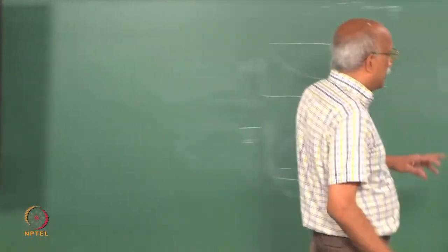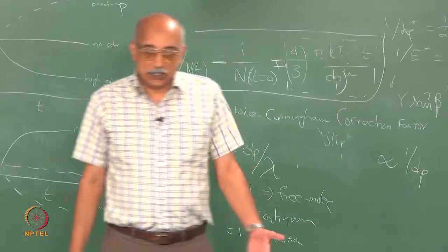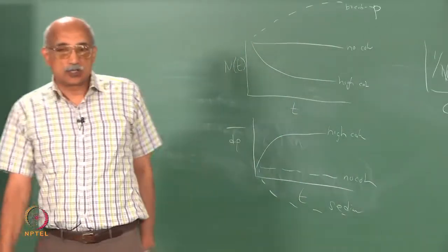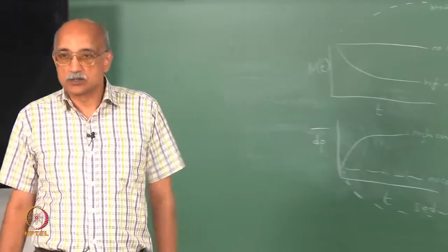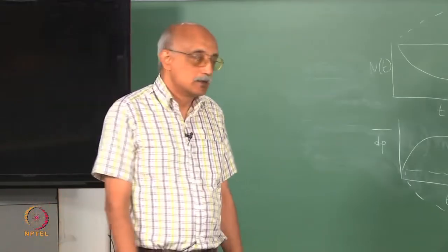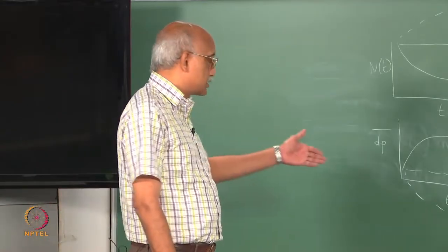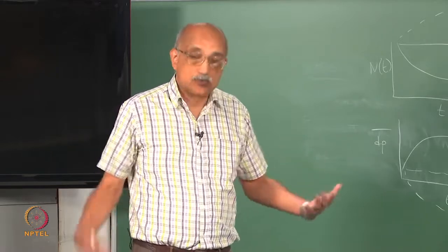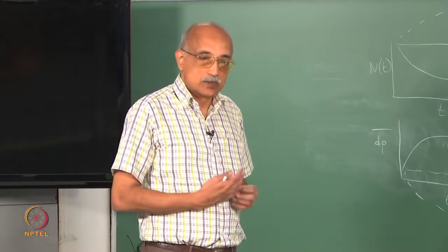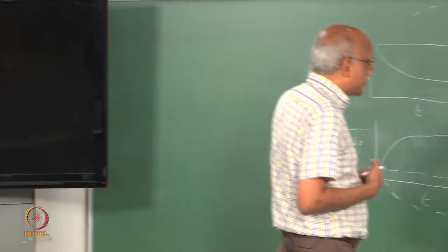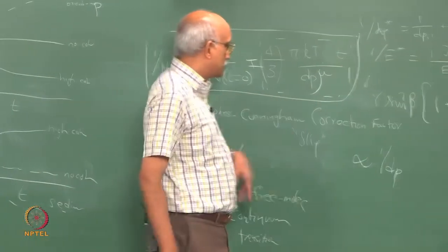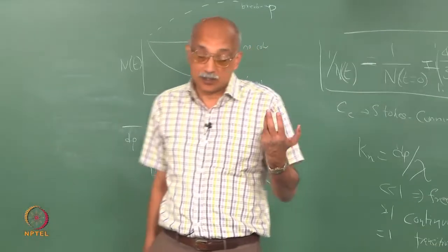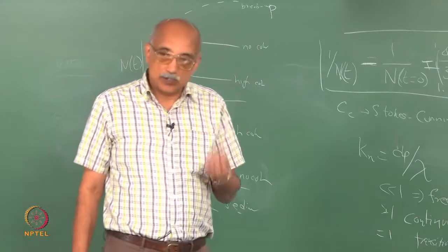Time is also in the numerator. Again, this is a trend we always see, that with the progression of time, cohesion increases, and that is again because as time passes by, the particles have more time to find each other and stick to each other. So, cohesion will increase as temperature increases and as time increases, and cohesion will increase as the particle diameter decreases.